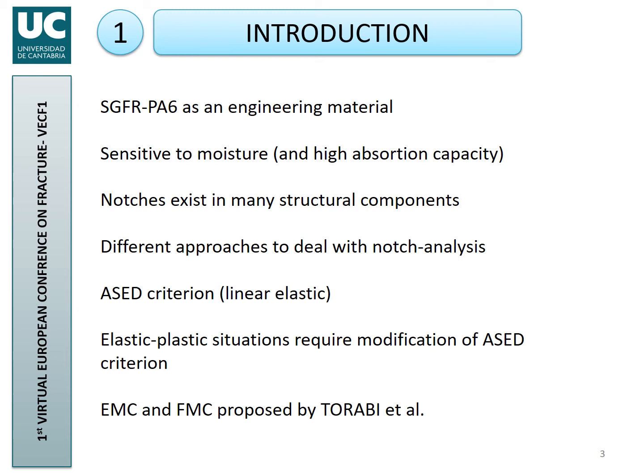The equivalent material concept works quite well in materials that do not have a linear elastic tensile curve, but have linear elastic fracture curves. The material analyzed in this work has non-linear curves in both tensile and fracture situations, and that's why we are using the fictitious material concept and not the equivalent material concept.